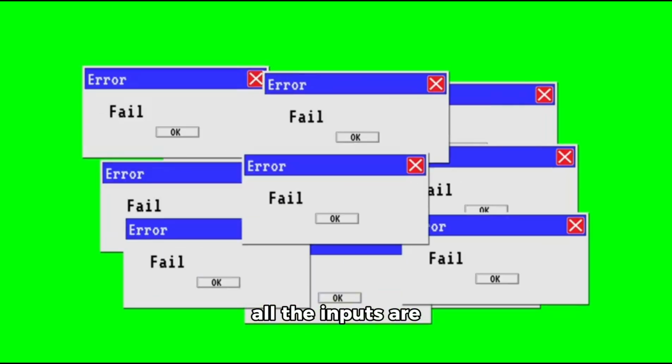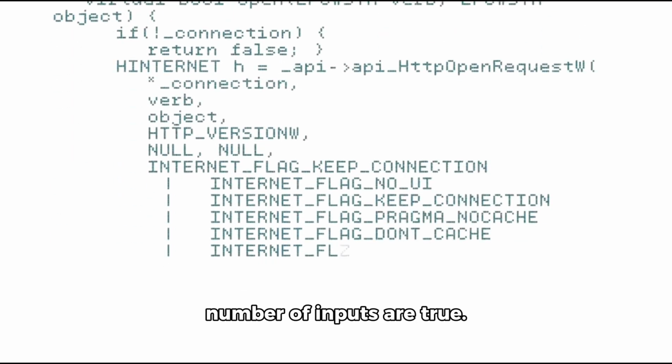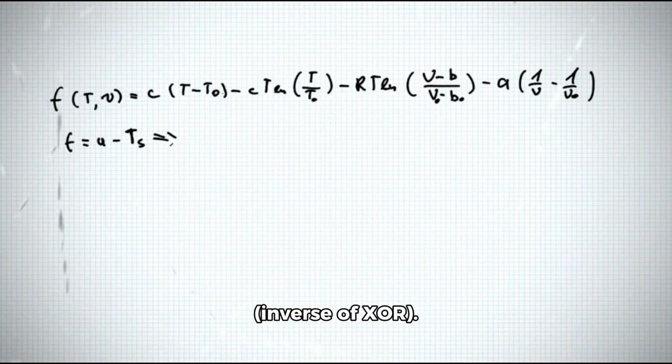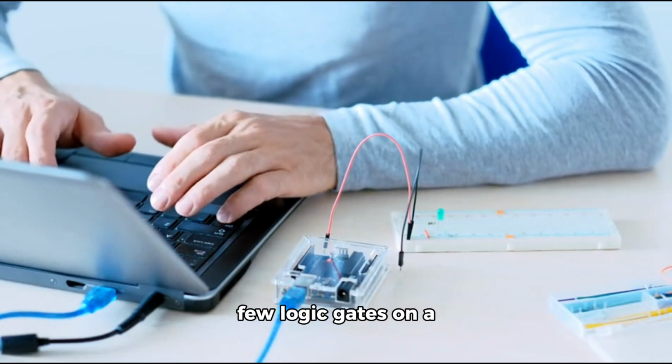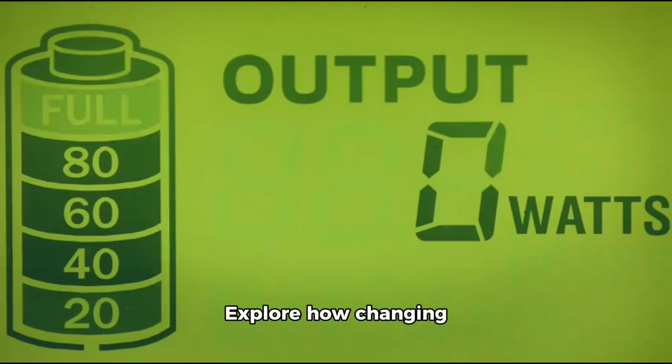NOR gate. Outputs true only if all the inputs are false, inverse of OR. XOR gate. Outputs true if an odd number of inputs are true. XNOR gate. Outputs true if an even number of inputs are true, inverse of XOR. Activity. Try creating a simple circuit using a few logic gates on a breadboard or using simulation software. Explore how changing inputs affects outputs.